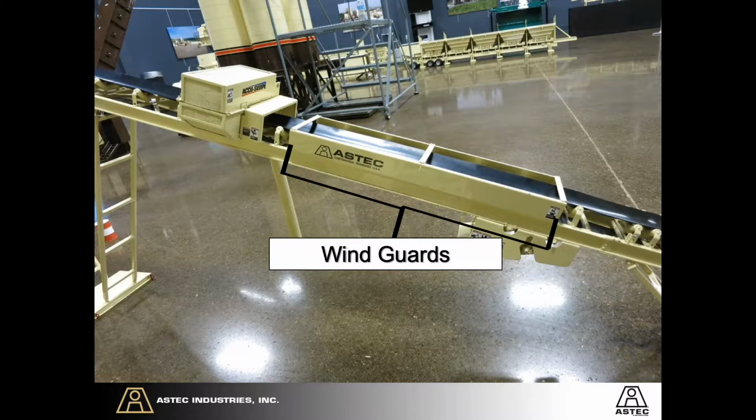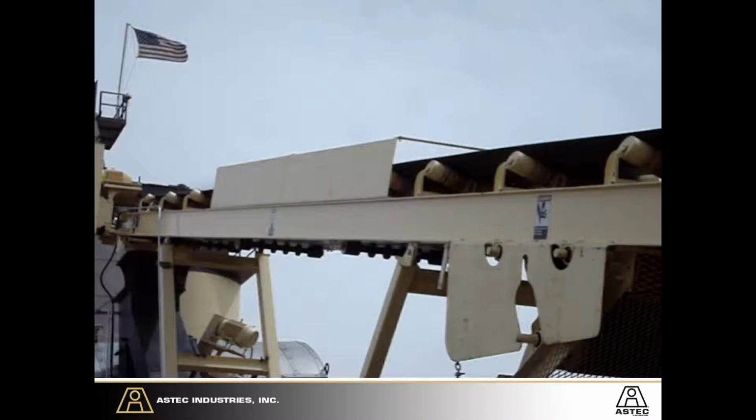Here's a good picture of the wind guards that we talked about. It keeps the weigh belt hidden, so it's easily disguised, and it usually is not maintained very well because of that. You can see here's the reasons in this picture, and it gives a little bit of an illustration. If you can see the wind on the flag, how it's blowing that flag straight. If we did not have these wind guards here, we'd get belt slap, which would give you inconsistent belt readings when you tried to do the zeros. So it could cause you problems when you're trying to make mix.